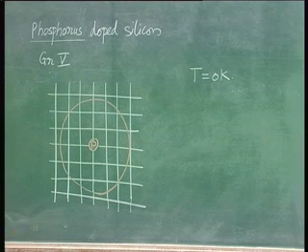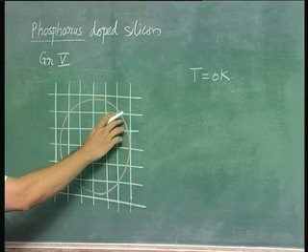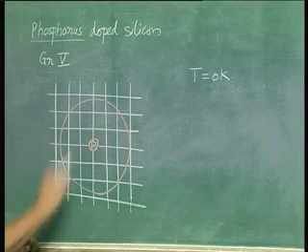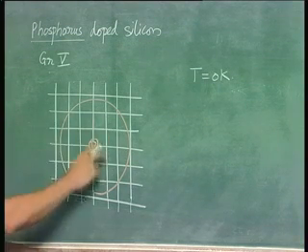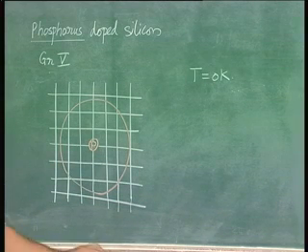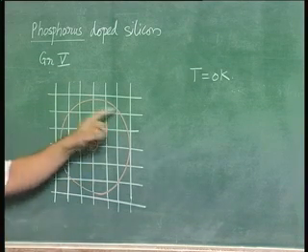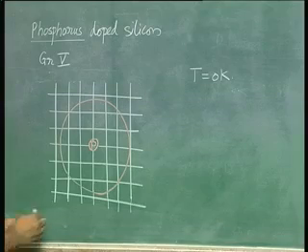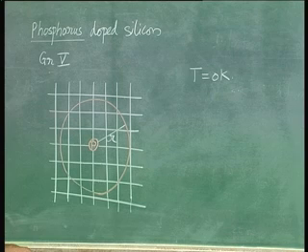Now it is important to note that the orbit radius is rather large and it is not as small as you have in a hydrogen atom. Now this is because the medium here is silicon and not vacuum. So one must consider the effect of the dielectric constant of the medium in which this particular electron is orbiting. So we are saying that this radius r is much more than that you have in a hydrogen atom.